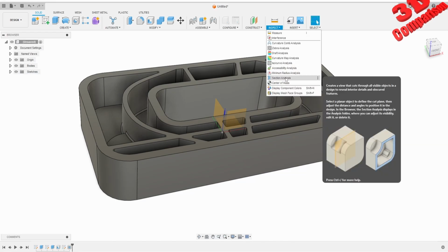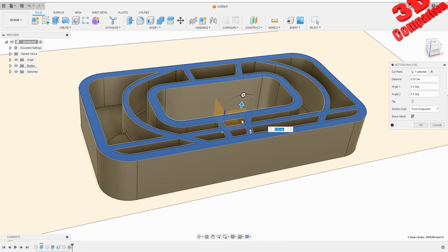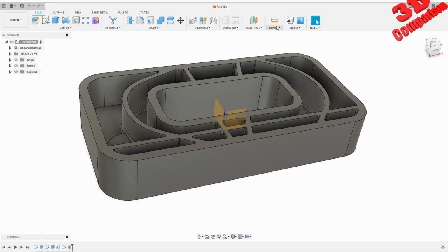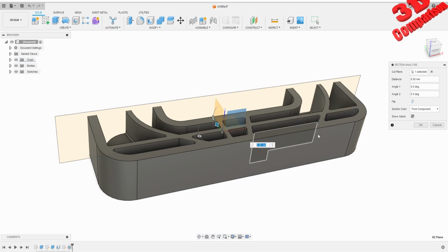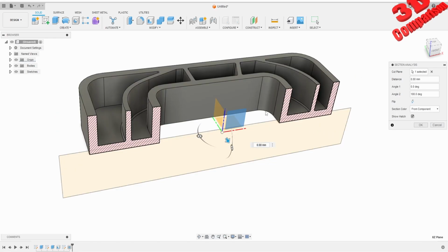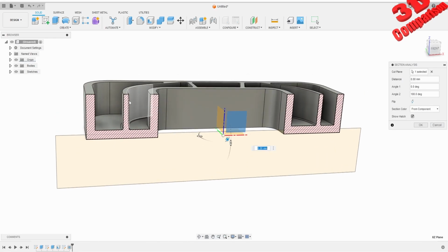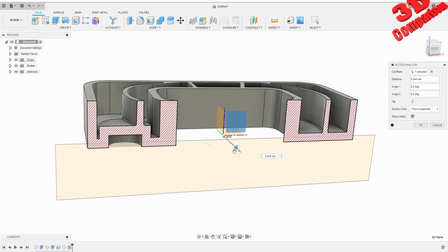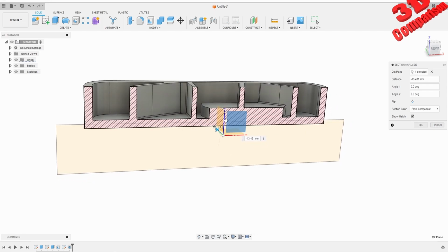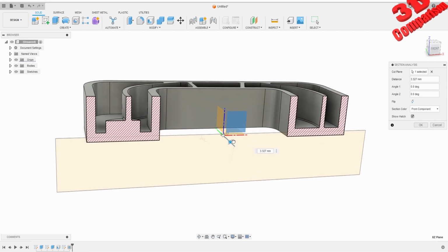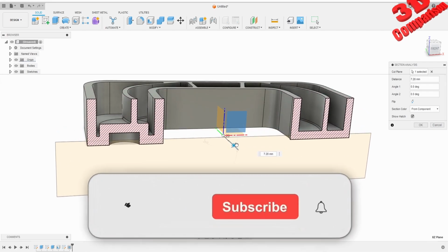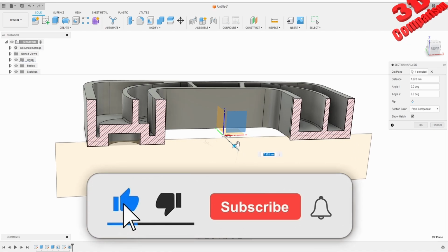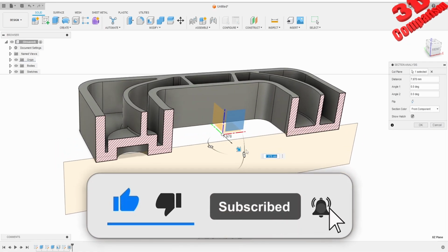And now if I go over here within a section, I will select that I want to define that section through a plane, so to this one. I also want to flip that. We're going to see this profile, so this will be a little bit narrower on the top and wider over there on the bottom, so that this is intended for plastic components that are drafted.